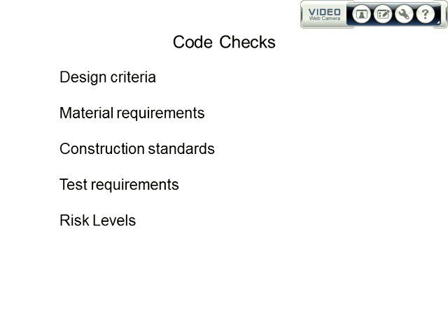Now, what you say is, well, you want to do the minimum change to the pipeline. So if the proximity distance is much greater in the change of use, that means you may need to think, well, I've got to reduce the pressure to bring the distance in, or I've got to apply protection. You've got to basically just apply design thinking at that point.